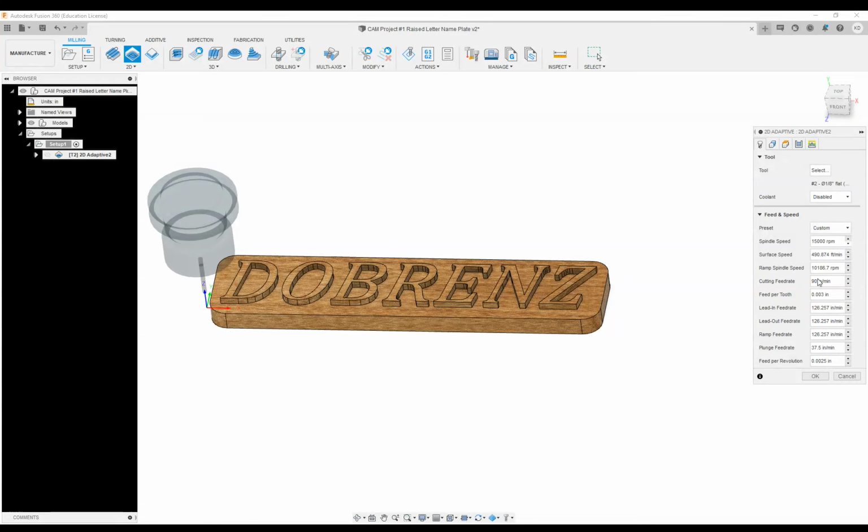It imported my desired feed rates, so I don't have to change any of this, which I definitely recommend, especially if you're working with pretty consistent materials: set all these rates. And I generally just set my feed per tooth and my feed per revolution in RPM, and then I get the surface feet per minute that I'm looking for, surface inches.